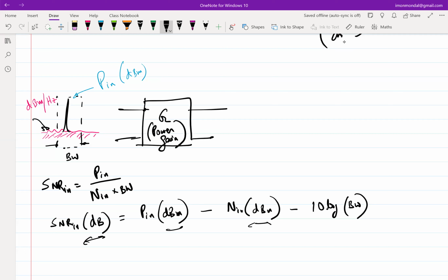When I say power, it means there is an associated resistance somewhere, right? So the input resistance is basically the source resistance of whatever is coming in, while the output is whatever you are driving. If there is no output resistance, but the output is a capacitor, there is no power associated with that. In that case, we just simply take the voltage and square it. Right. So that's the typical assumption. So G is now the power gain.